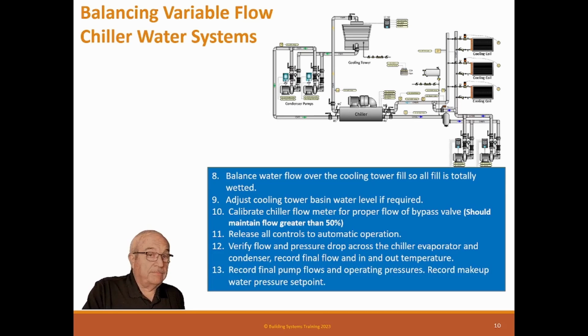So again, just like that, this is a little simpler system to balance. The only thing is, it gets a little more complicated if you have more than one chiller. Then you have to see what the design is. Where the design was set up to maintain two chillers, it should be one per chiller. It makes it much easier. But multiple chillers are more difficult on this system. On the last system, it doesn't make any difference.